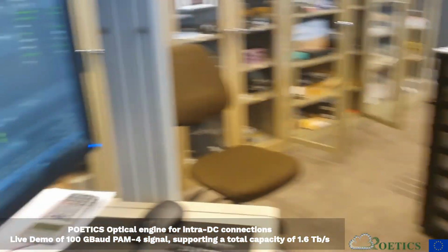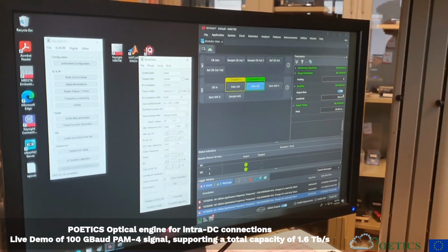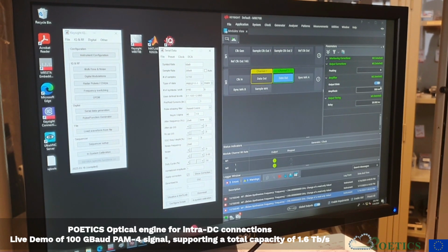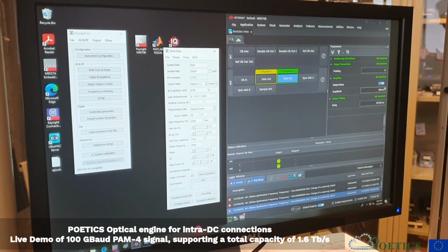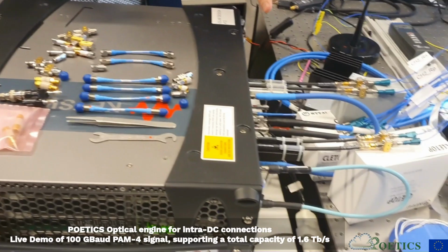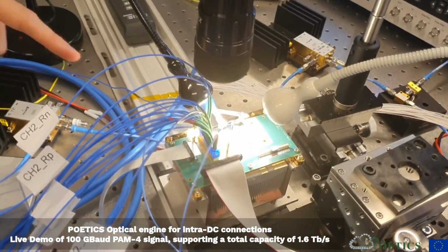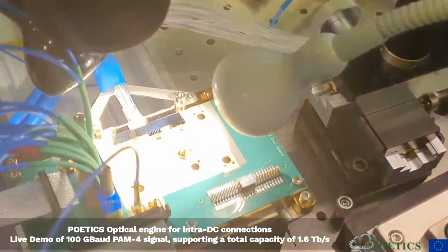On my left side, you see the user interface of the arbitrary waveform generator that we are using to create two data streams that we provide to the analog multiplexer. With the arbitrary waveform generator, we do some pulse shaping and re-equalization in order to create high quality signals for the analog multiplexer and to compensate for the losses and signal distortion that we see through this coaxial cable array. On the board, we then see the transmission lines going to the electronic chips.